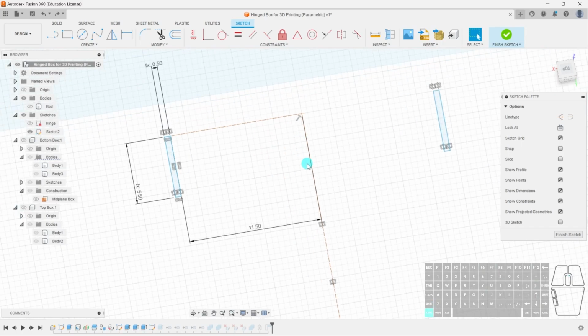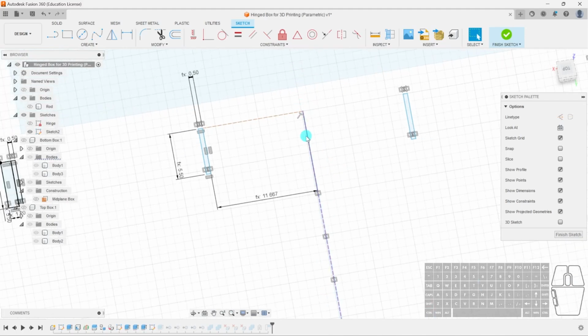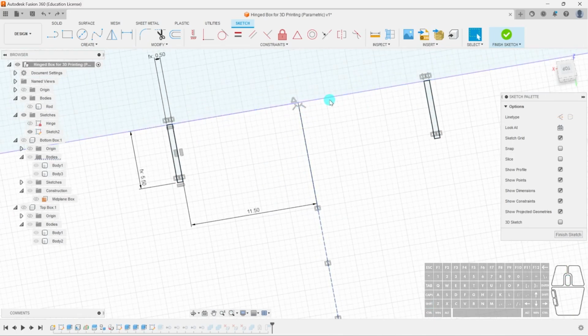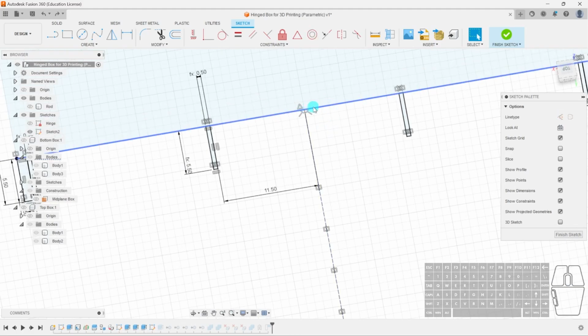Okay, so what I've done is this hasn't actually been aligned to the sketch. You can see here, it's moving the mirror line instead. I don't want to do that. I also don't want to fix this because it's actually based on the previous sketch. So what I'll do is I'll show my projection line, and this is why projections can be quite confusing sometimes. In this case, I know my line is here. It's just for your sake I deleted it. But in this case, I know the projection needs to be there.